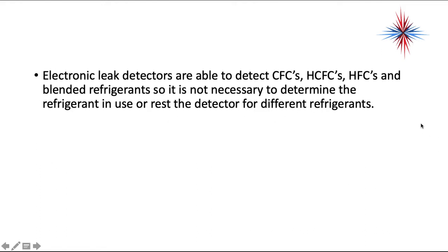It's important. Electronic leak detectors are able to detect CFCs, HCFCs, HFCs, and blended refrigerants. So it's not necessary to determine the refrigerant in use or reset the meter for different refrigerants.